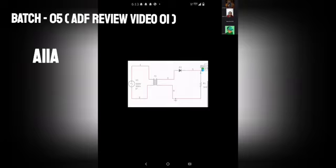During the positive half cycle of the AC wave, the diode becomes forward biased and allows current to pass through it. The current then flows through the load resistor R1, 1 kilo-ohm, producing an output voltage across it. During the negative half cycle, the diode becomes reverse biased and blocks the current, so no current flows through the resistor. As a result, the output is not continuous, but a pulsating DC. It means only the positive half cycle of the AC signal appears at the output. The ground connection completes the circuit path.